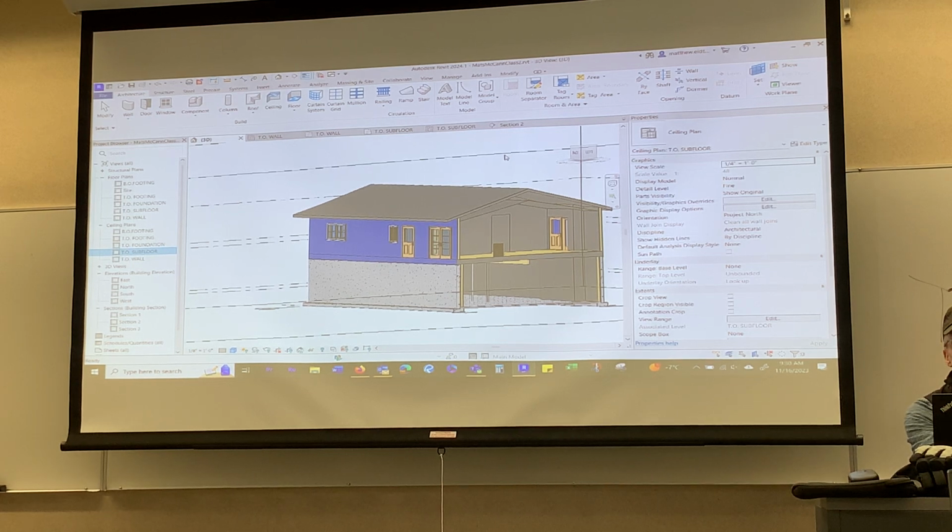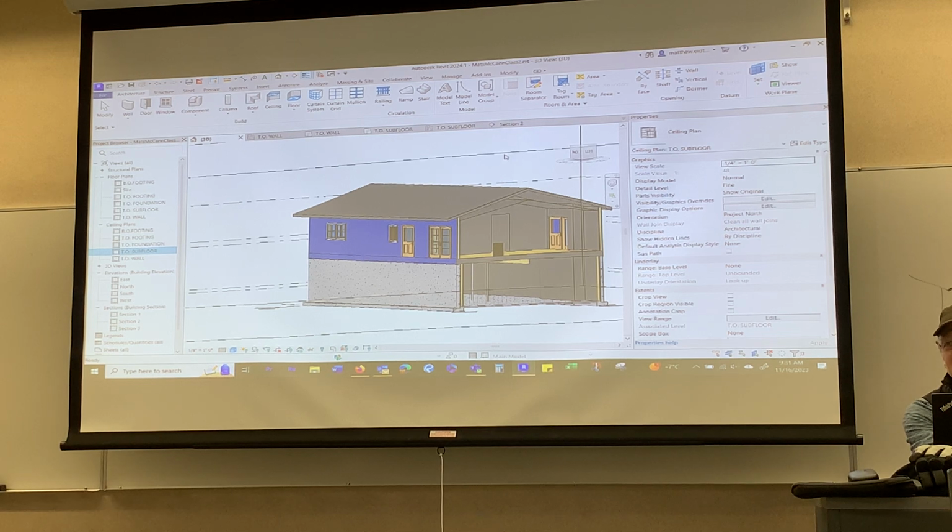And remember when you build a house, that framing, and you're checking head height, in case you end up going into residential or something like that. Make sure you remember that the beam and the stairs at rough are not the same when they finish, and the building inspector knows that. So there's gotta be drywall on the beam, and there's gonna be flooring on the stairs. So you're gonna lose some there. So I've got stuck on this before, because usually it's pretty close, especially a house like this.